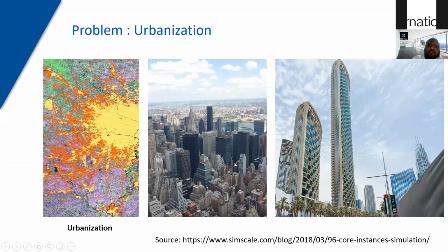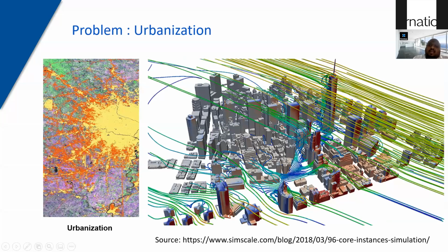As you grow your buildings taller and taller, you have to deal with different sorts of wind pressure and wind tunneling effects, which happen in condensed spaces. This has been noticed even in the UK recently because of this high urban movement to the city centers. Pedestrian comfort has been thrown out for a toss. People have been thrown away with winds tunneling through buildings. So you have to look out for facade or curtain walling systems which are tested for high wind pressures.